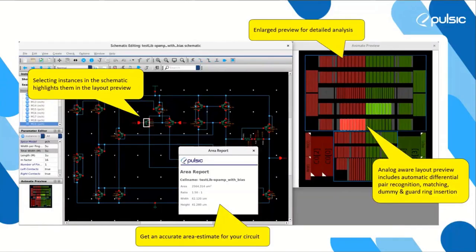Absolutely, you can, and you have a lot of control over that. I didn't point this out on this picture here. The gray devices are dummies, so it's put dummies at the ends of the rows by default, but you can also tell it to always do it as a project file setting, or on a case-by-case basis, to put a ring of dummies around those sensitive substructures. So if you want a ring of dummies around the differential pair, it'll do that. Another way of doing that would be to put a guard ring around each of those structures, and you can do that as well.